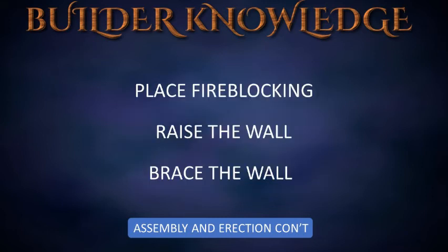Raising the wall. Now that the wall is ready, it's time to raise it up. The rule of thumb for raising a wall is, one person is required for every 10 feet of wall. Order may vary from job to job, but usually, longer exterior walls are raised first. Then shorter walls are raised and the corner posts nailed together. The order of framing and raising interior partitions depends on the floor layout.